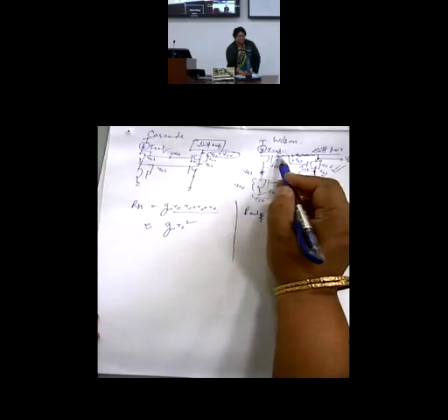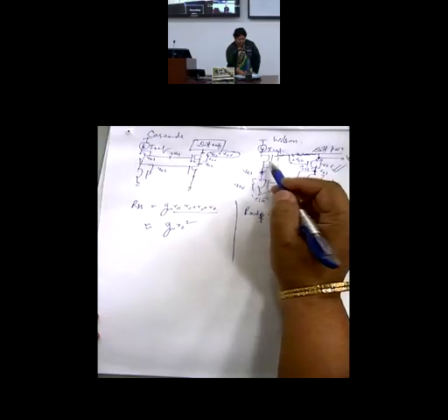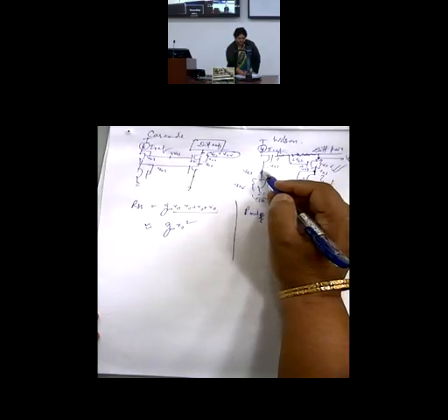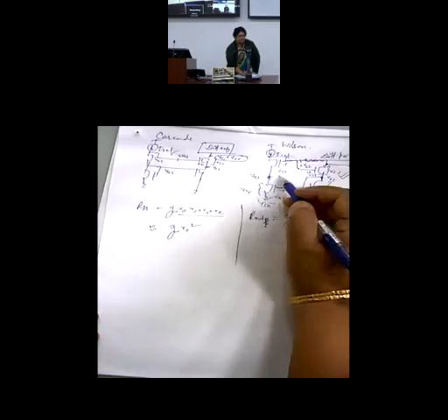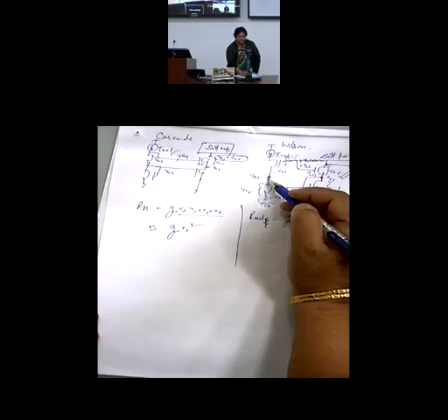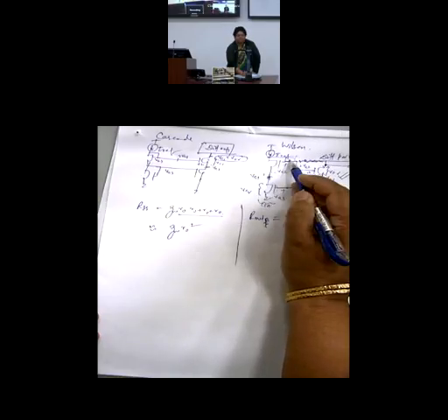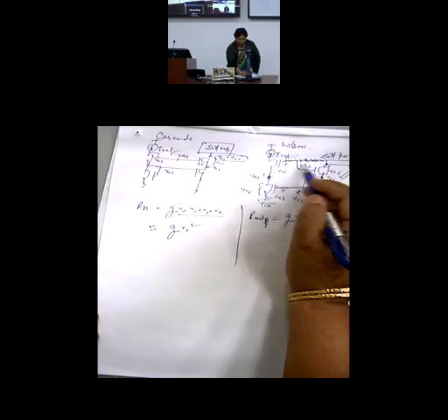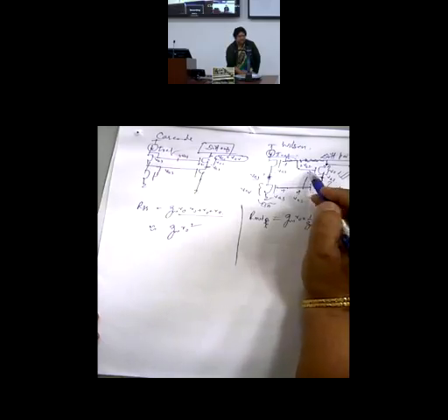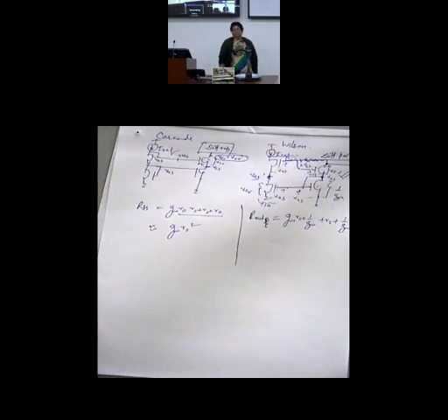This negative value comes here because this VGS has to be constant, since it is constituting a constant current IREF. So when you change here, because VGS has to remain constant, if it goes up, this also goes up. If this goes down, this also goes down by the same amount. As if the effect propagates from this node to this node, and then it goes to the back gate of this transistor. If this is negative, VGS will decrease, current will decrease. So any initial increment will set a negative feedback and cause the gate to reduce. As a result, the current will roll back.